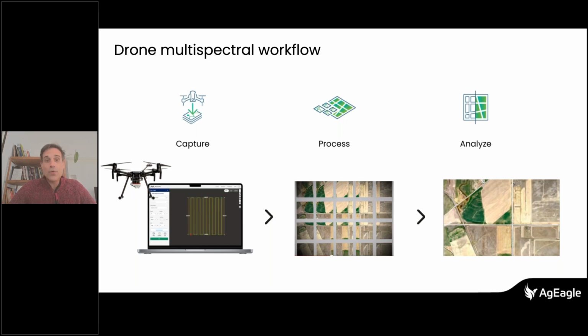So the reason why we ask everybody to fly with 70% overlap, which is a lot, especially if you don't want 3D data, because for agriculture it's usually okay with a 2D map, is because we want every pixel to be in at least 15 different images, and we can make a mean value so that all these illumination differences between the images are leveled out, right?